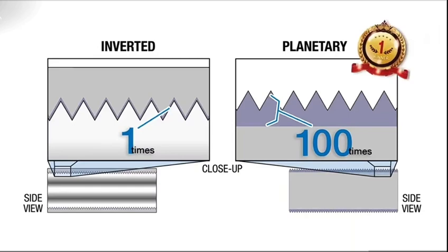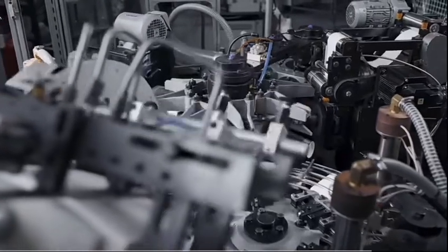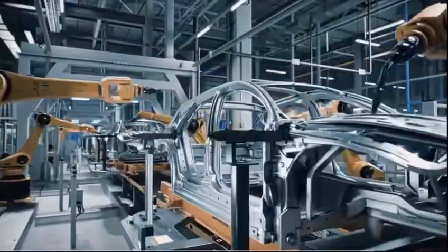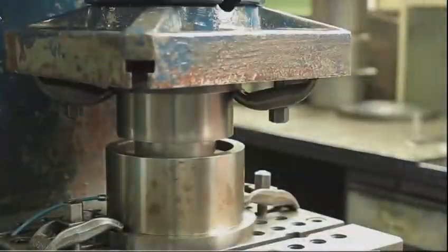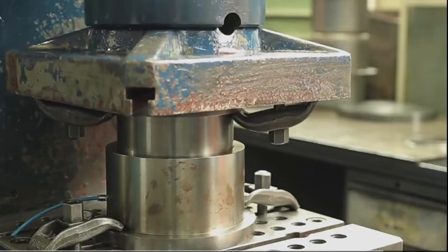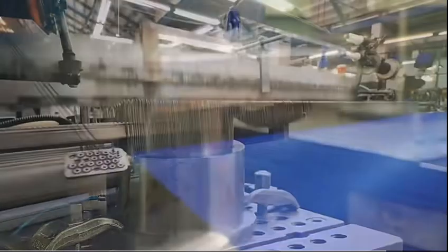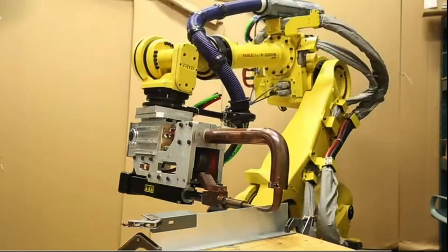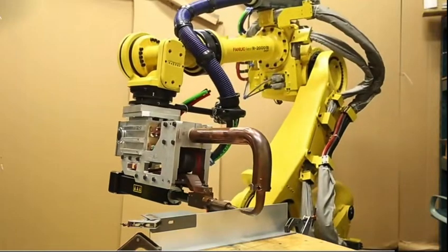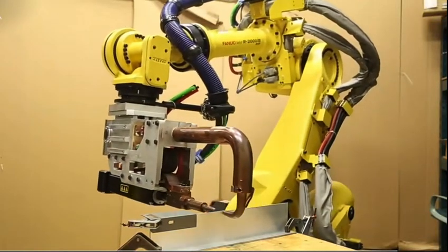from shock loads. This can be especially important in applications where most of the working time is spent on a small section of the thrust rod, like a pressing or high-frequency oscillation application. For applications that require high force, repetitive cycles, and long expected life, planetary roller screws are ideal.